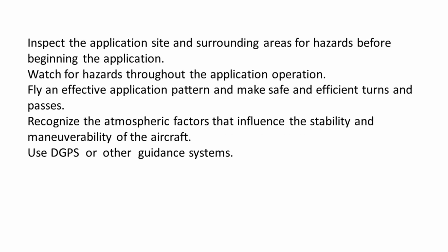Inspect the application site and surrounding areas for hazards before beginning the application. Watch for hazards throughout the application operation. Fly an effective application pattern and make safe and efficient turns and passes. Recognize the atmospheric factors that influence the stability and maneuverability of the aircraft. Use DGPS or other guidance systems.